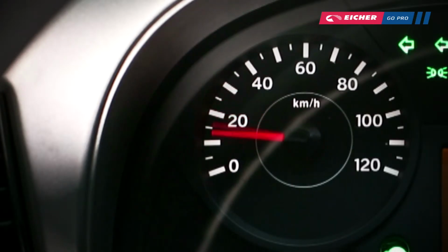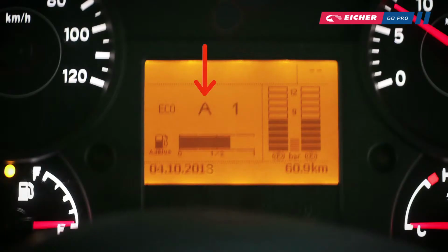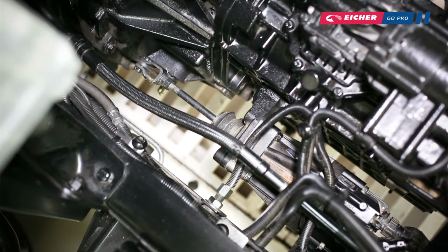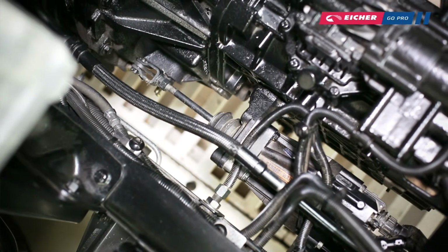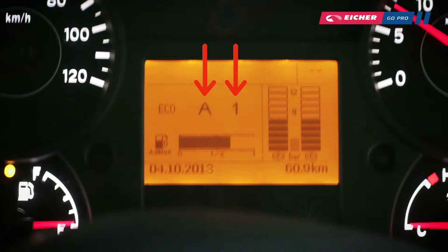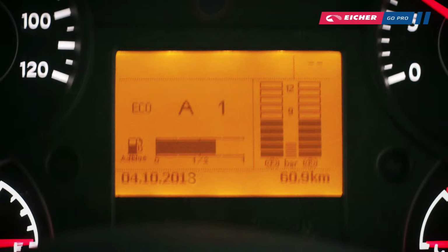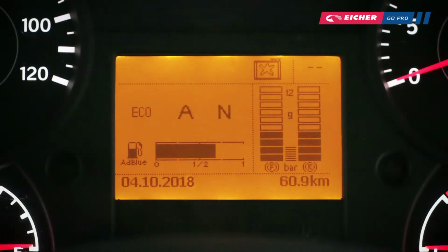When the vehicle speed decreases towards zero and a gear is engaged, the clutch will open automatically by SLU to prevent engine stall. When the vehicle is stopped while in automatic mode or a gear engaged, the SLU initiates a shift to the appropriate starting gear automatically.